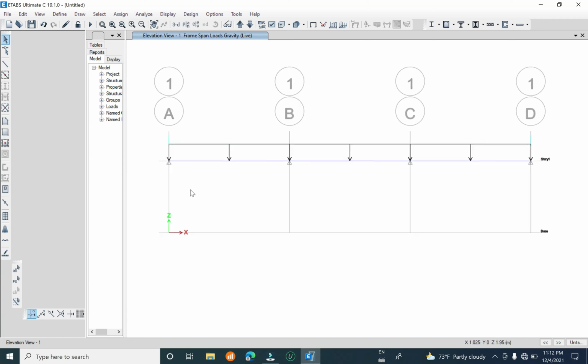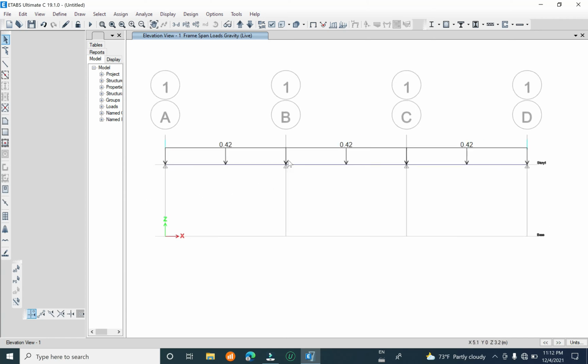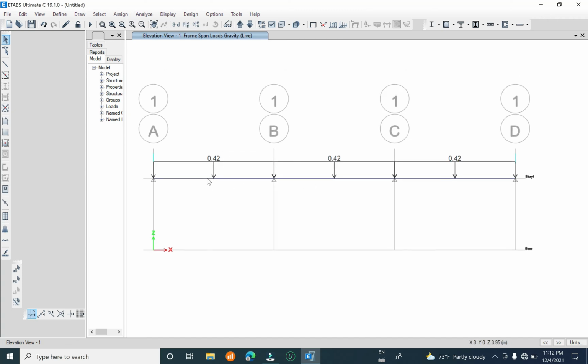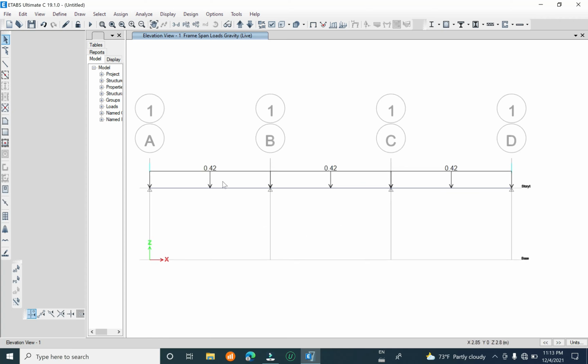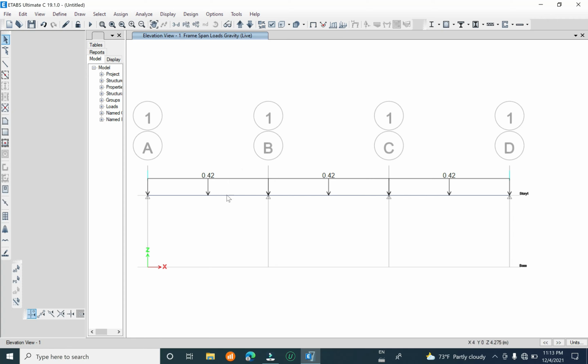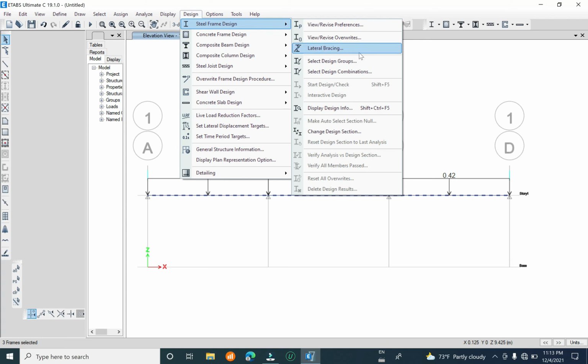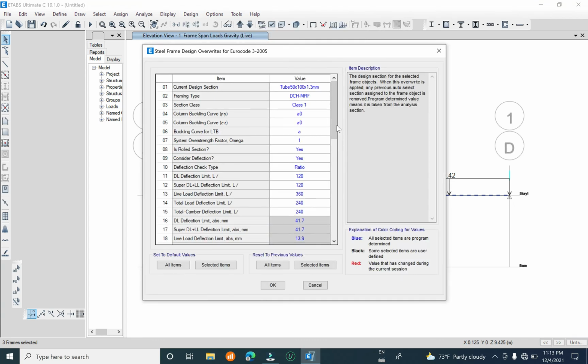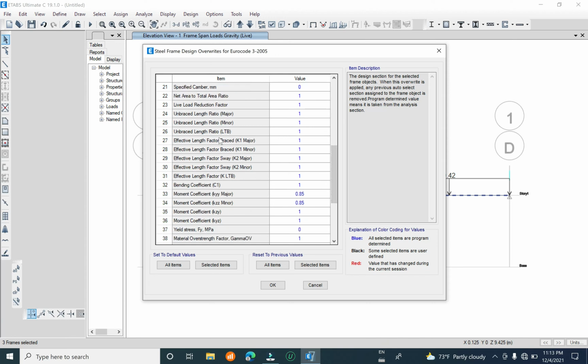everything here is clean and clear, and from one support to the other support you can consider the restraint at the top, because we have added a sheet at the top of the rafter. We can support the tube, so we have to consider it in the design. Now let's input this parameter directly in the steel frame design preferences, or you can select the review and revise. And bracing, okay, you can add here.